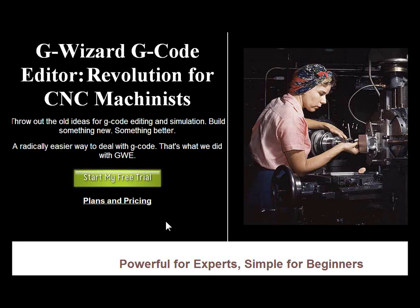And that's better than nothing for sure, but it doesn't reflect what's actually going to wind up being on your machine. So if there's any problem at all with how the post works, if there are bugs in the CAM software, you're just not going to see that if you run strictly the CAM simulator. You can get the program over to the machine only to discover there are some things going on that didn't show up under your CAM software simulator.